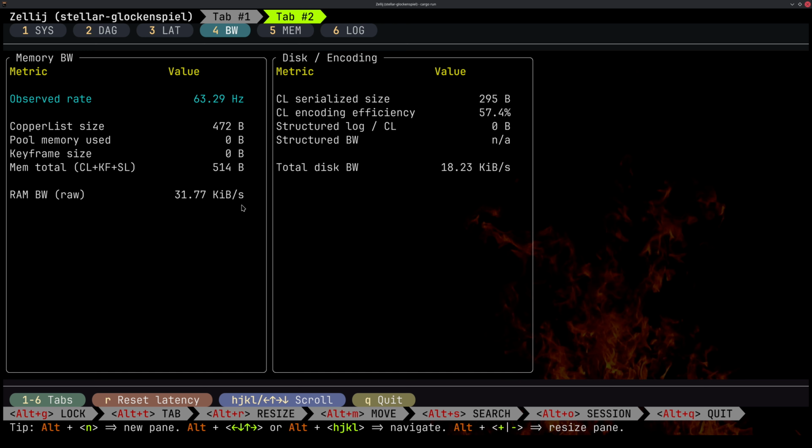And you see at the bottom how much bandwidth just the execution of the Copper list is pushing through your system. Here it's ridiculous, but you can imagine if you have images or heavier data structures, you can try to see if your robot is hitting the limit of your computer. So check out the channel bandwidth, for example, and if it starts to be in the same ballpark, you see that you can hit a bandwidth limit of your system. A very cool way to see that in real time, and you can check what is happening. Here it's very stable because this robot is very predictable.